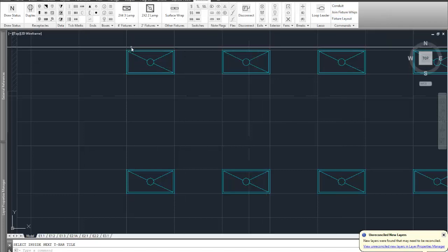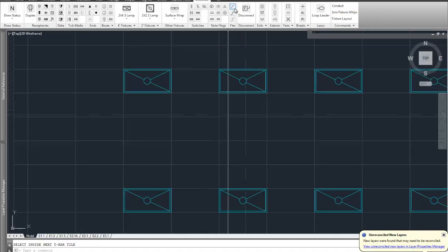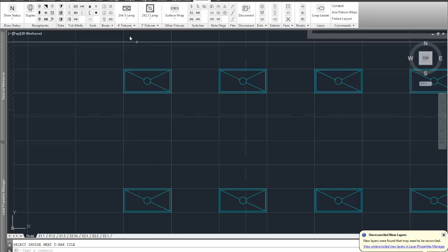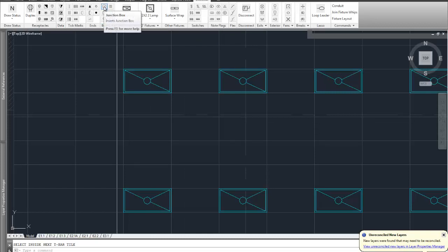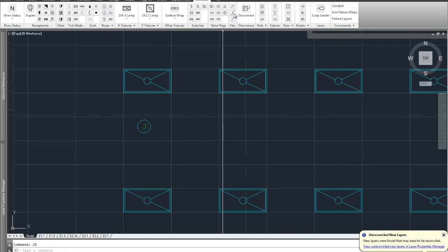The easiest way to get started here is to look at the ribbon. There's commands on here that are going to be used. First, let's just look at hooking up a light. Over here we have junction boxes. Place the junction box. Over here we have two different kinds of whips. This one in the middle says flexible conduit, and this one says fixture whip master satellite pair. If you hover over those, you can barely see a difference. There's a little F in the middle of that one, and this one doesn't have it.